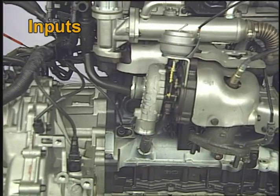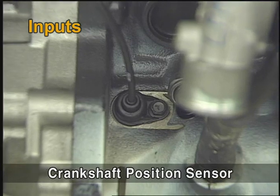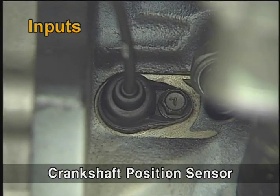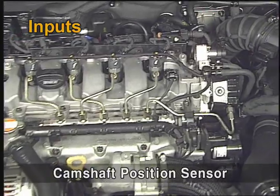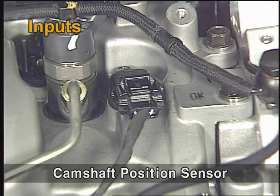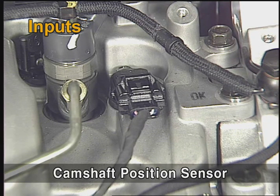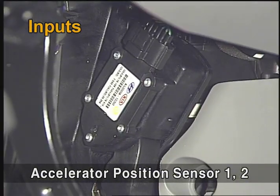The ECM uses various signals from the crankshaft position sensor for detecting the engine RPM and the exact position of the piston, the camshaft position sensor for detecting and distinguishing the positions of the piston of number 1 cylinder and that of number 2 cylinder exactly,